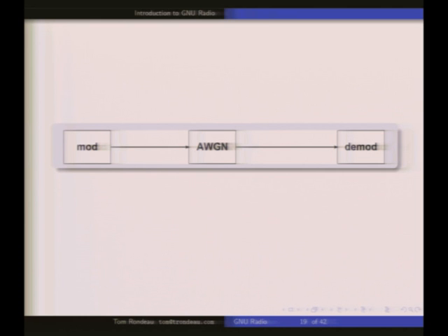But you kind of want to start there, but you really want to go farther. For one thing, let's replace AWGN with, this is already in GNU Radio, where you can actually set a frequency offset, a timing offset, and a phase offset that would be inherent in the different oscillators of your radio. So you're never going to be on the same frequency. The sample times are never going to be exactly correct on these two sides. So you've got to fix that problem first.